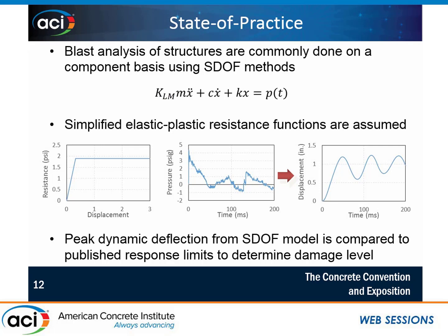And then ultimately what you want to calculate is what your displacement is, okay? And from that displacement, you're picking out your peak transient displacement that you get in your response and converting that into an equivalent support rotation, and then comparing that support rotation back to published criteria.